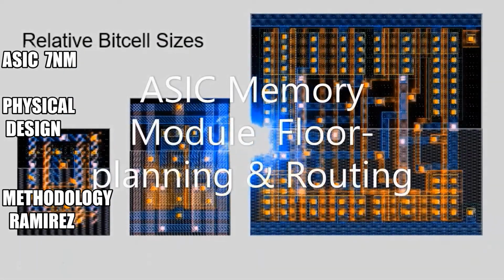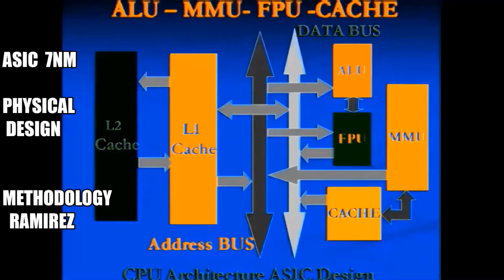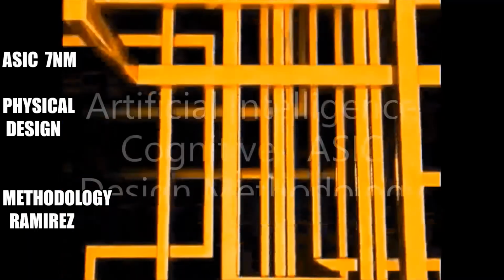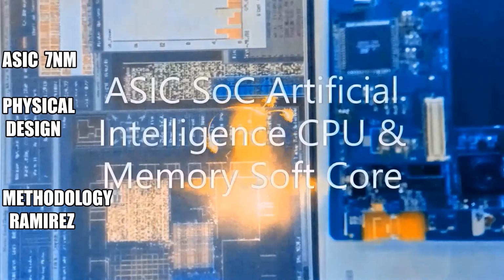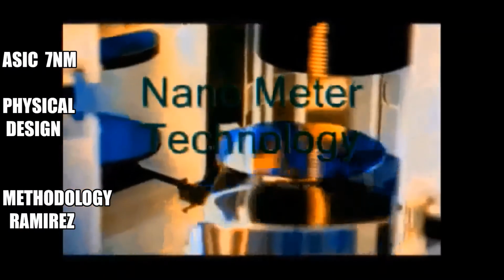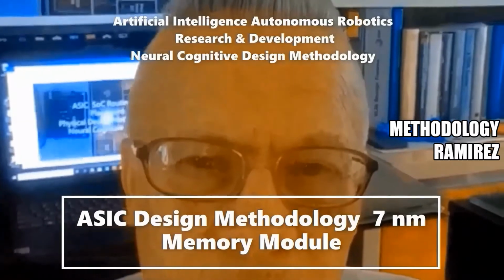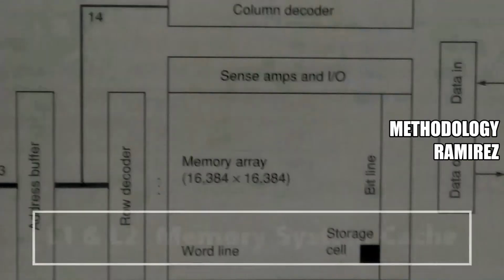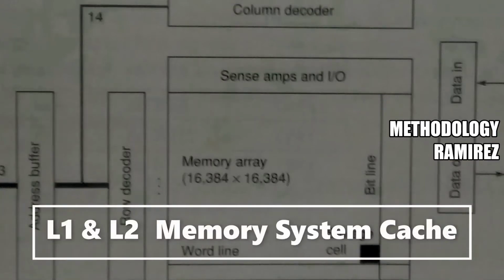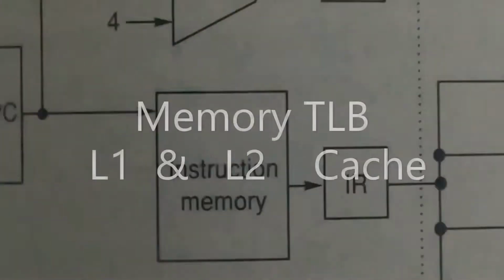Fourth, the hit time reduction trace cache technique implemented in this design, this ASIC methodology design. A challenge in the effort to find instruction level parallelism beyond four instructions per cycle is to supply enough instructions every cycle without dependencies. One solution implemented here is called the trace cache.